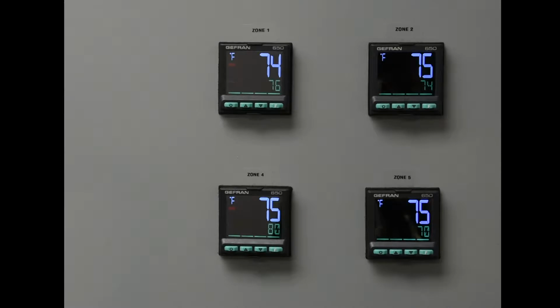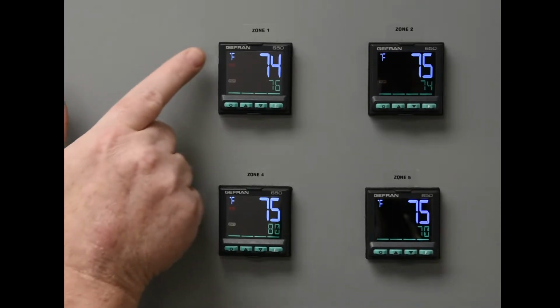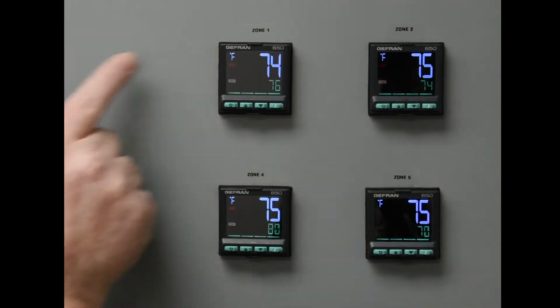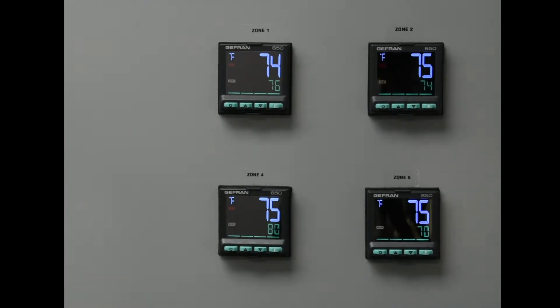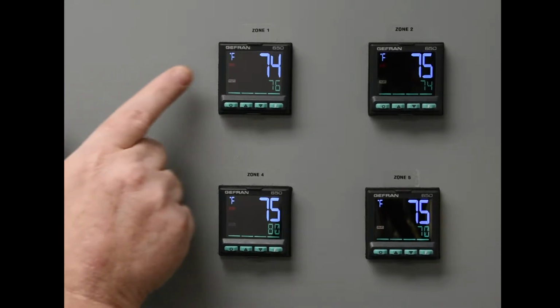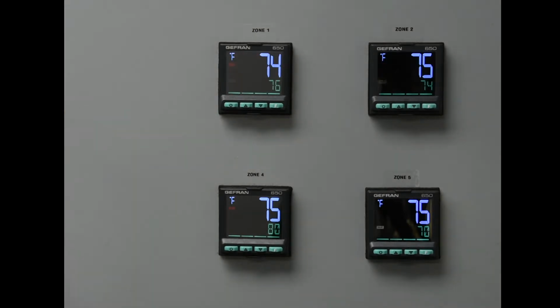Do not apply power with blankets unless the temperature sensing is in place. I will now explain the display, keys, and their functions starting at the top left and going counterclockwise. In the top left is the temperature unit of measurement, or it will display the program which is running. Just below that is the state of outputs, output 1, 2, 3, and 4, which will show which devices are powered. Below that are the controller function states.